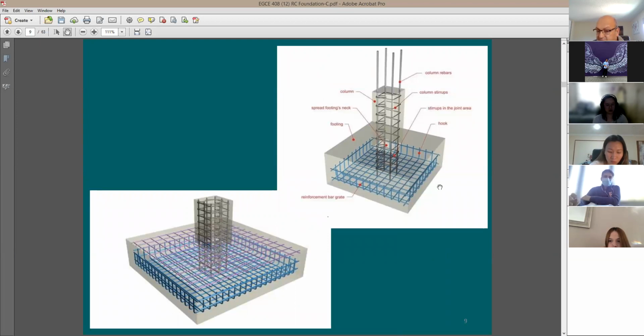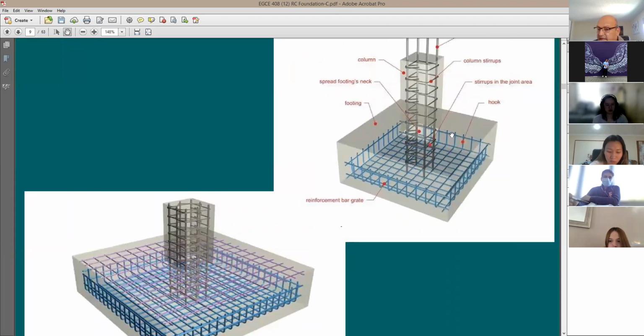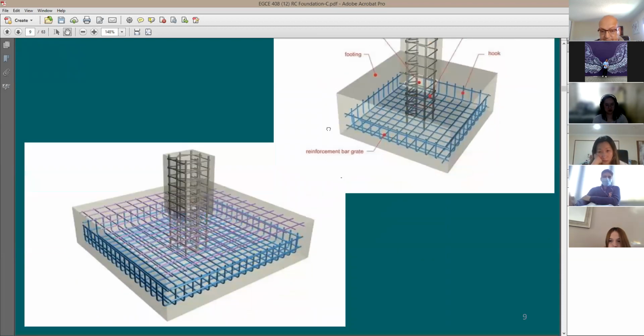So if you look here at this footing, there is no top reinforcing. We didn't really add it because we're expecting tension to be at the bottom and compression to be on the top. I'm going to show you here in a second the estimated deformed shape of the foundation after you apply some loads. In this case here, you see that we have a top mesh and a bottom mesh. So here's a top mesh in a different color from the bottom mesh.